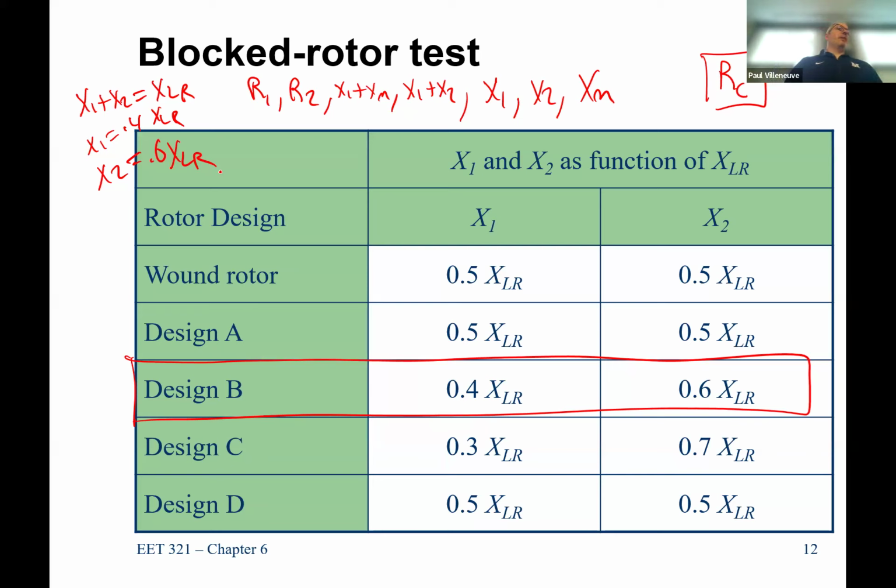Yeah, the nameplate, but normally you would specify a motor design, and you would specify if you had different characteristics. If you wanted a steeper drop off, you'd go to NEMA Design A. If you wanted the standard one, which has a lot of starting torque, a pretty good lock rotor torque, a breakdown torque, and then fairly good efficiency, you go with Design B. If you want all your starting torque to be available at the beginning, when you start it up, so you want your pull-out torque to be at the start, you'd go with a NEMA Design D.